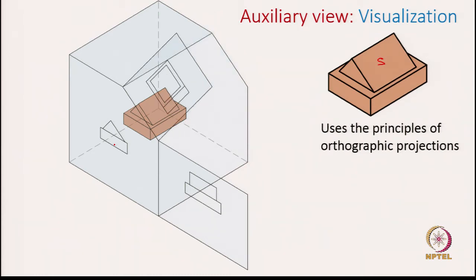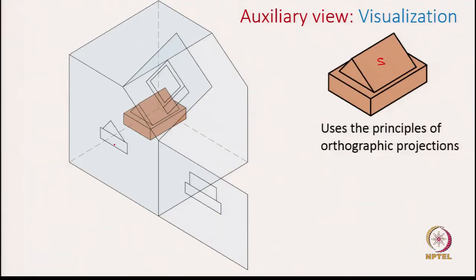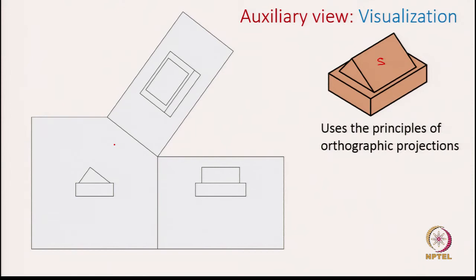Okay. So, I hope you are following. What we have done now is we captured the front view, side view and the auxiliary view, but noticing that front view is the primary view because the surface of interest appears as an edge in the front view. We decided that we will open the rest of the views in the same plane of the front view. So, we opened the right side view as well as the auxiliary view, and finally, after rotation this is how it looks like. So, finally, this is your front view, right side view and the auxiliary view.